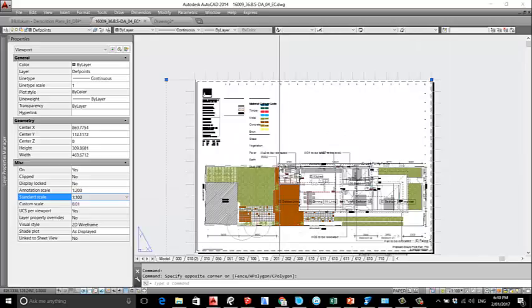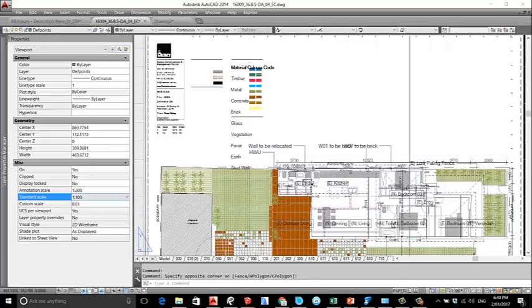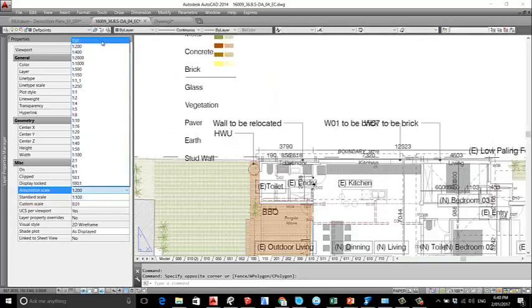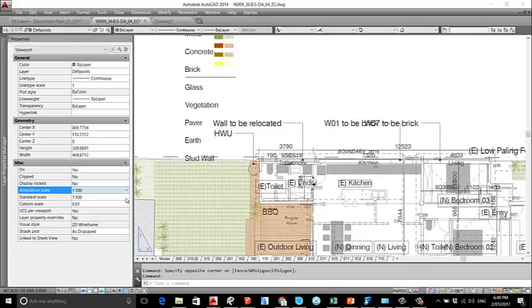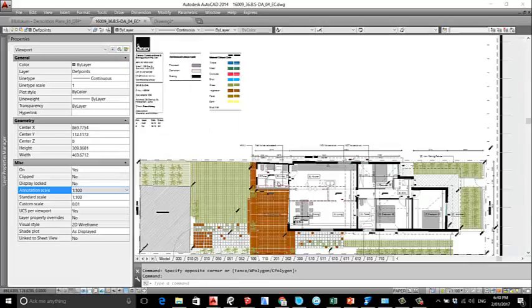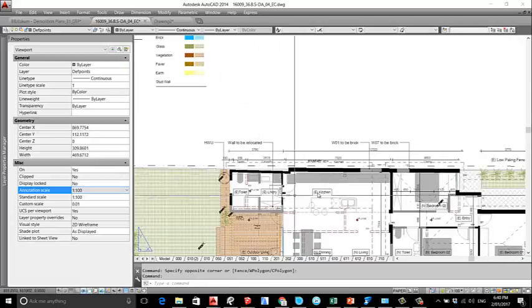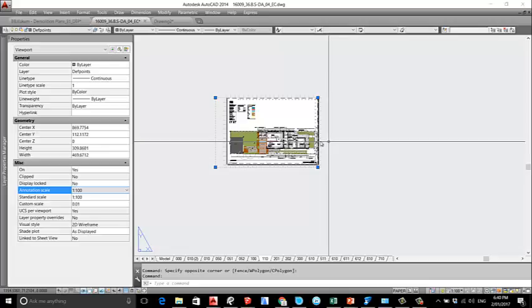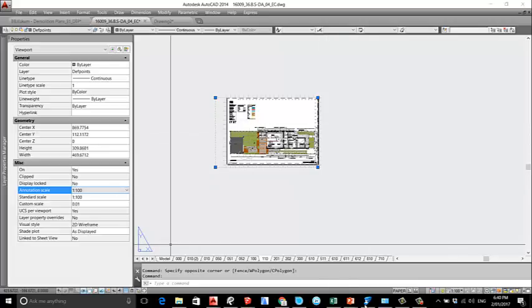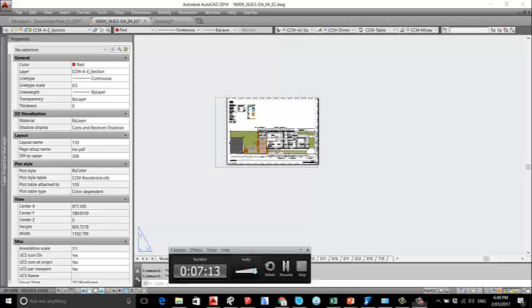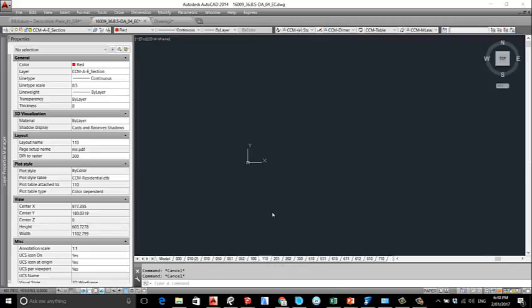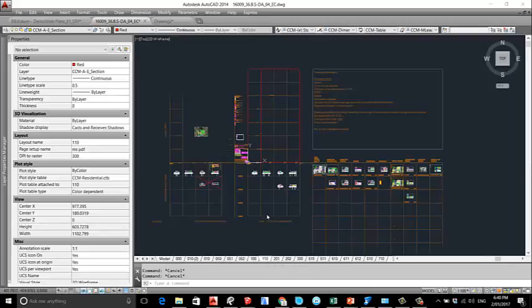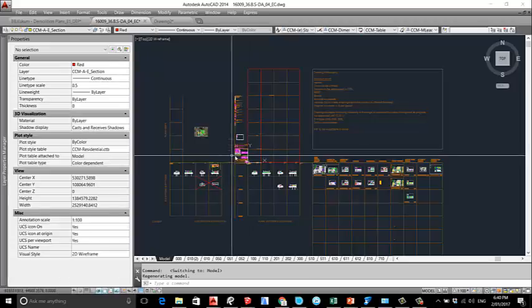The annotation is massive, and it's because it's 1:200 and the scale is 100. So that is a bit of a mess. We put it back to 100 and 100, and voila, it looks perfect. So every block we have done normally prints just right on the annotative scale. And just for 1 second. Now let's go back to the model, and let's do one more last thing.